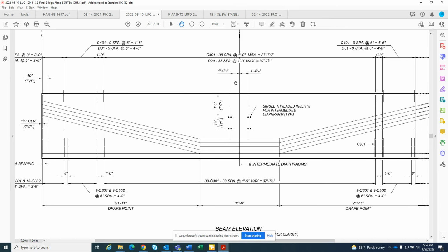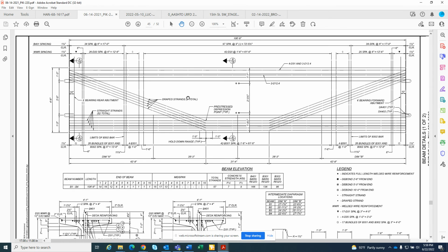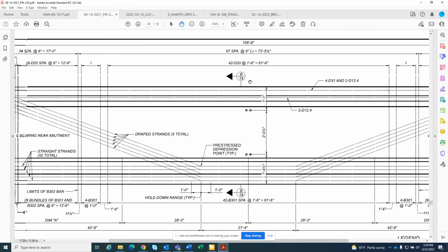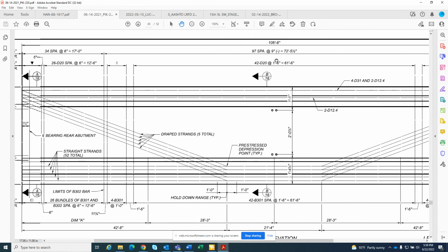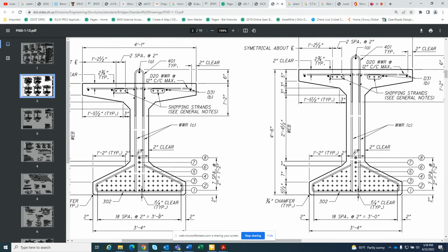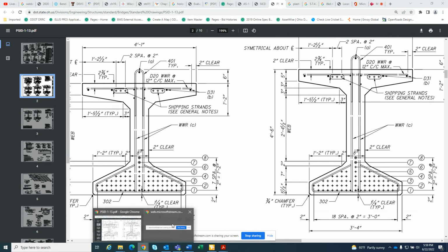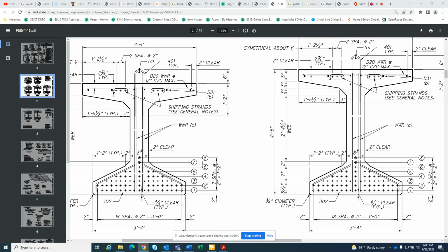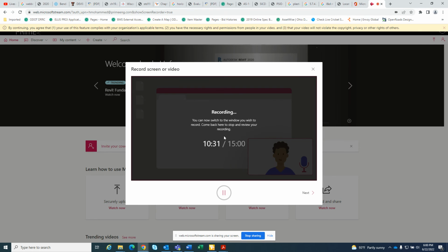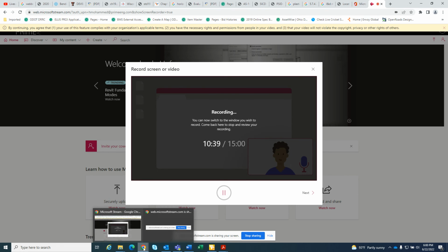Yeah, I think that should be it. So that is preferable, but this is not the end of the world when you have 9-inch spacing. If it is not working, you can make it 9 inches. It'll have a different spacing than the D20 D-bars, which is the main reinforcement. I'll be waiting for a few more. I'll get some response from Sean Meadows tomorrow, and then see what he says. Based off that, we can say number 4 can be worked out, or number 5 can be used. In short,